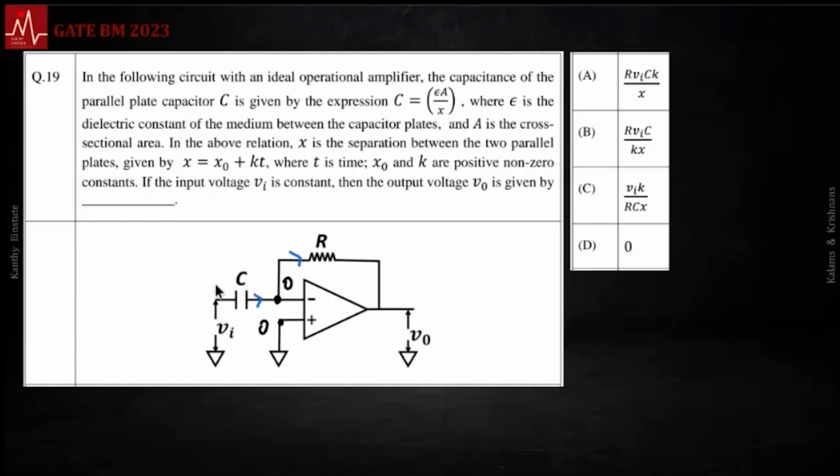Okay. Here, notice Q is CV. Q equals CV. Then, our current I equals rate of change of charge. Your capacitor is a function of X. This is a displacement sensor. Yeah, parallel plate capacitor. Then displacement changes with time. The input voltage, on the other hand, is kind of activating this capacitor. Okay, this is, let's say, constant.